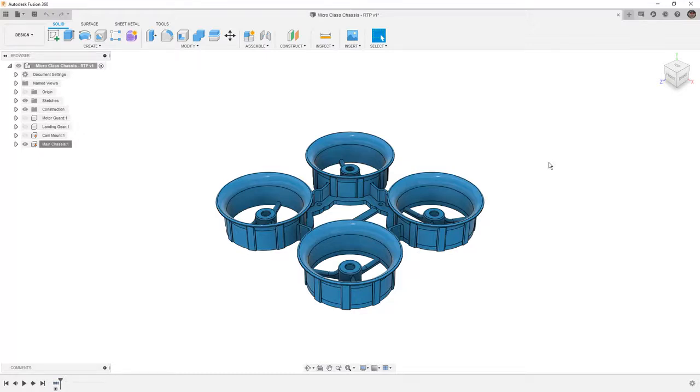Print a small part that has some curvature, some different geometry on it, send it out in different resolutions, make a 3D print, and identify what that means for you. For a print like this on a small desktop printer, this could take anywhere from 4 or 5 hours at a low resolution up to over 15 hours with the extremely high resolution if the printer can handle it. So it's not a good idea to waste that much time sunk into a specific print if you're not sure what the resolution values will be.